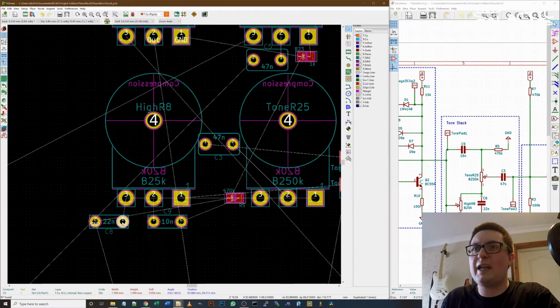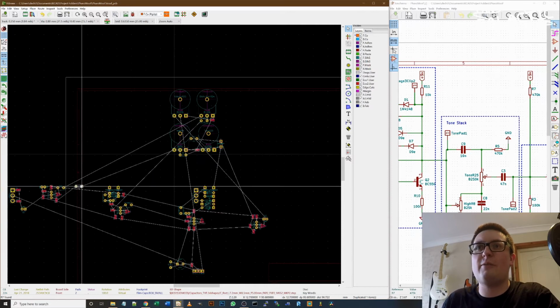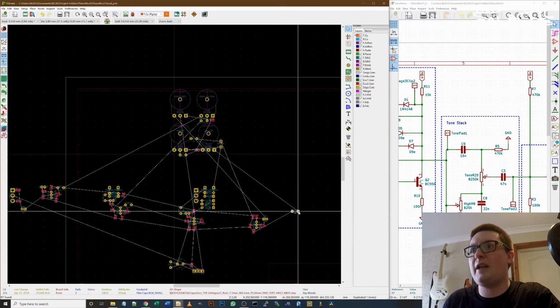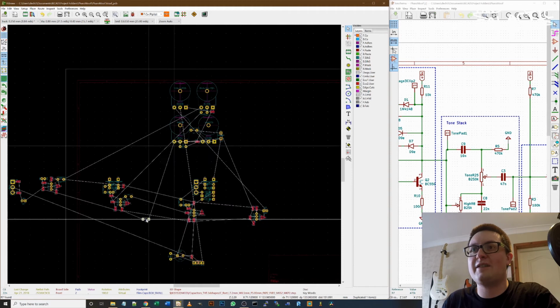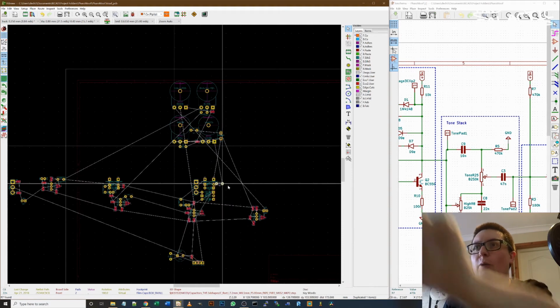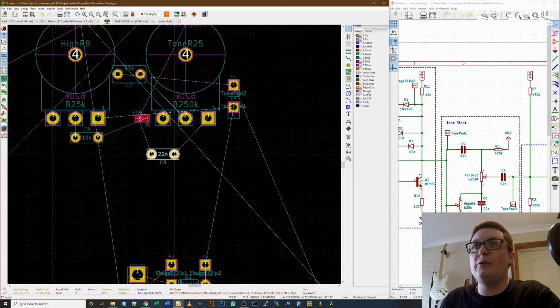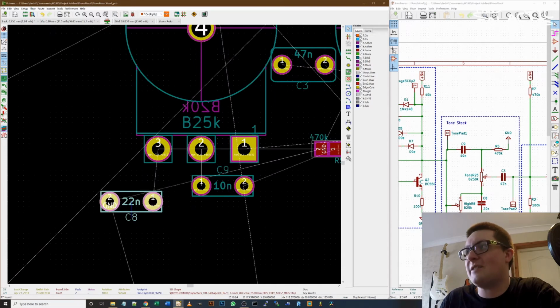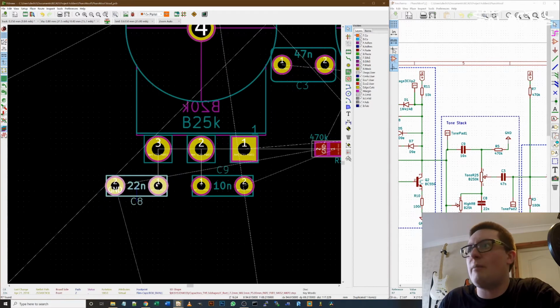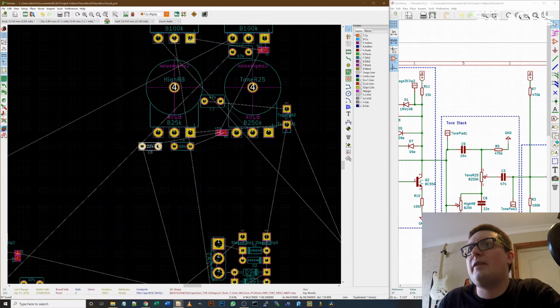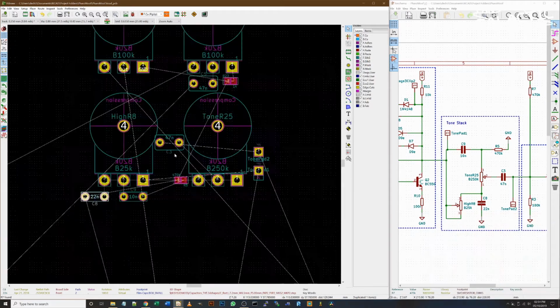So I always want to keep the other wire as short as I can, because there's only 2 points that can connect to, and if you move this around you can see the net will jump to other potential places that ground can join. But it'll always stay attached to one of these 2 pins, because they're the only pins it can attach to. So I'm always trying to minimise the length of whatever pin isn't a ground or a power supply line.